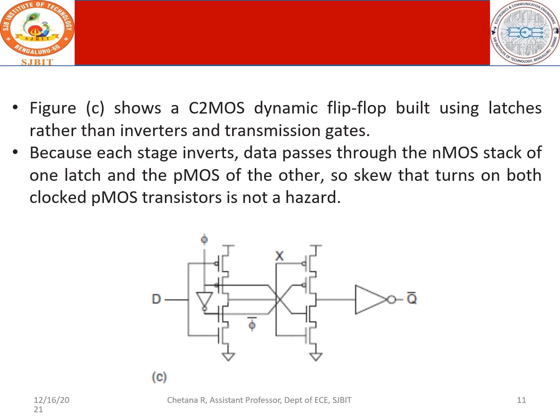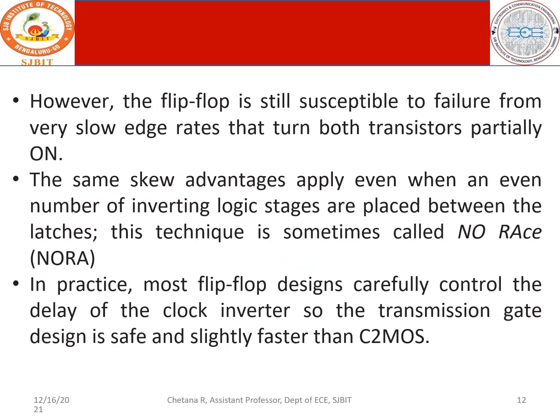This is somewhat a design which is better, as claimed by the author, because each stage inverts, and data passes through the NMOS stack of one latch and the PMOS of the other. So skew that turns on both clocked PMOS transistors is not a hazard. So in each stage data passes through the NMOS stack. You can analyze with respect to the clock being 1 and 0, and PMOS transistors are not considered a problem. However, the flip-flop is still susceptible to failure from very slow edge rates that turn both transistors partially on.